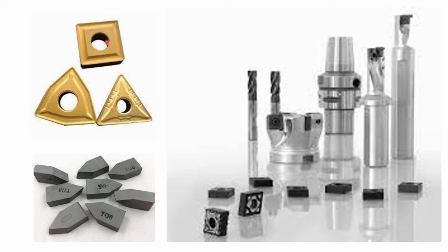And this one is for the steel grade, where they use TiC or TaC as the additive added into the tungsten carbide and cobalt, and then it is compressed into an insert like this one. Usually the cutting insert will be placed on a tool holder like this one, for example this one for milling, before we can use it for the machining process.